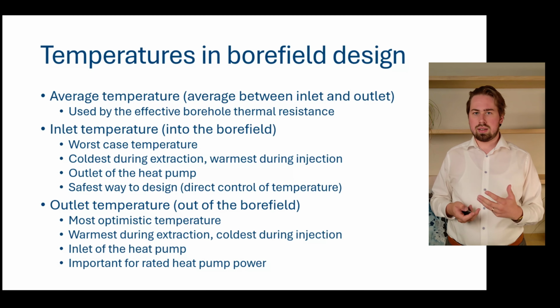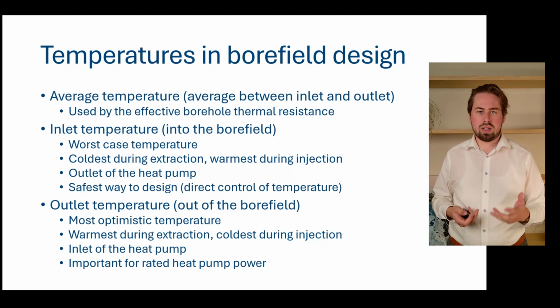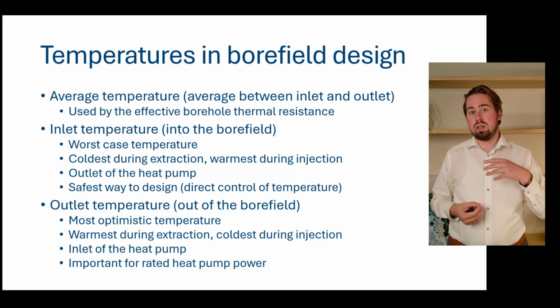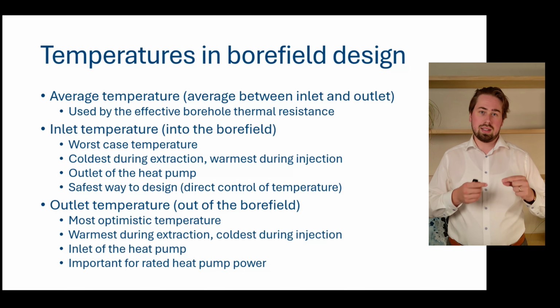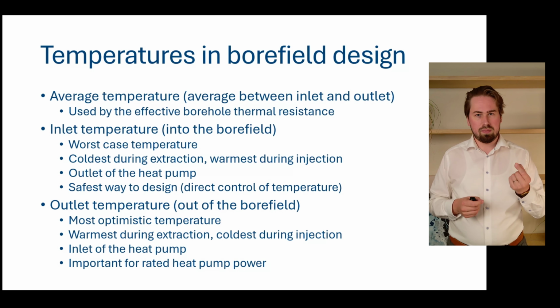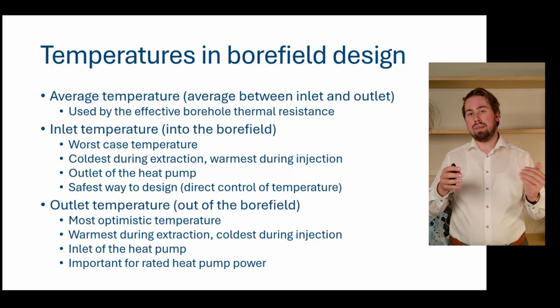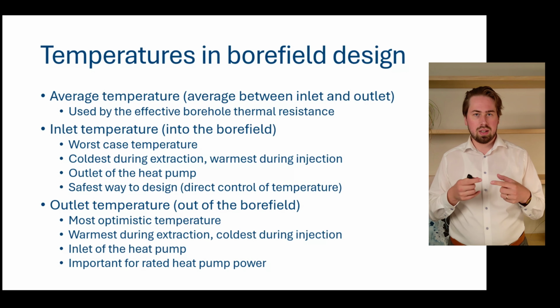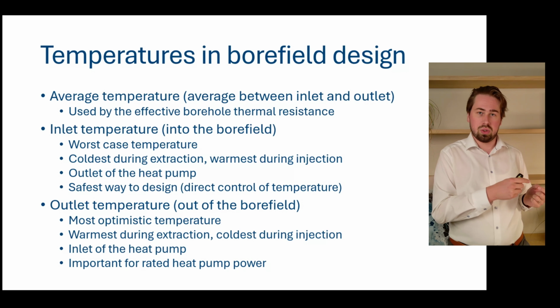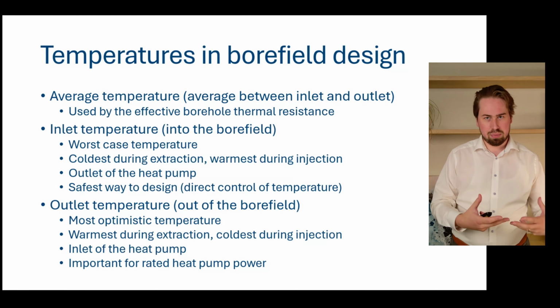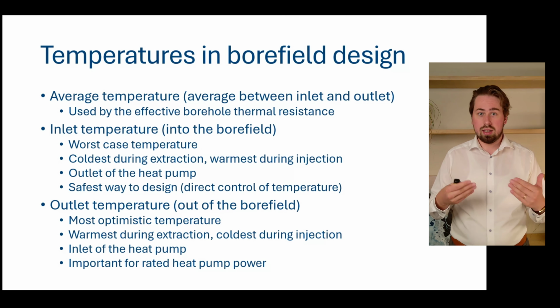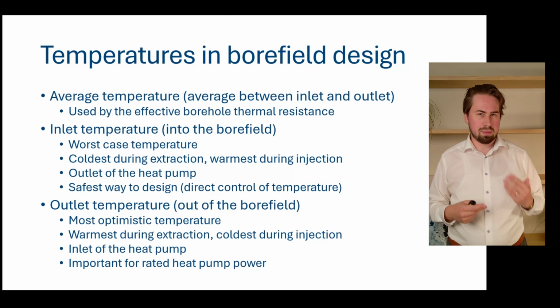Now, why is this temperature potentially interesting for you? It's because the rated power for heat pumps is typically defined as the fluid coming into it. And the fluid entering the evaporator of your heat pump is the same fluid that comes out of your borefield. So the borefield outlet temperature is exactly equal to the fluid going into your heat pump.